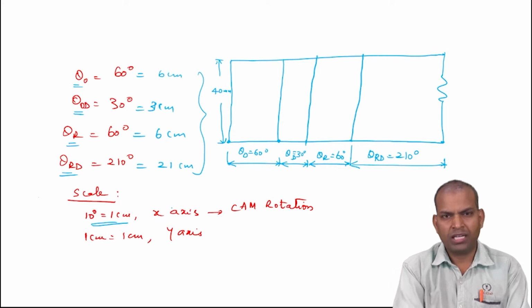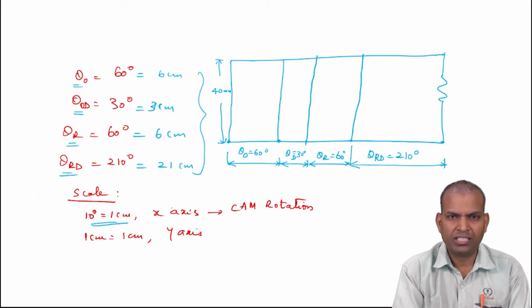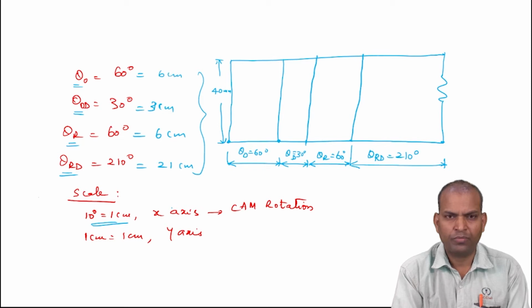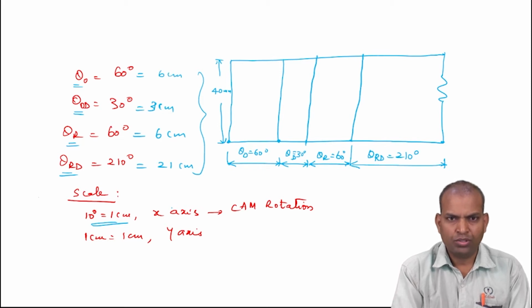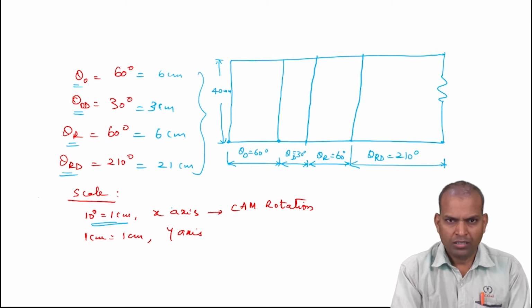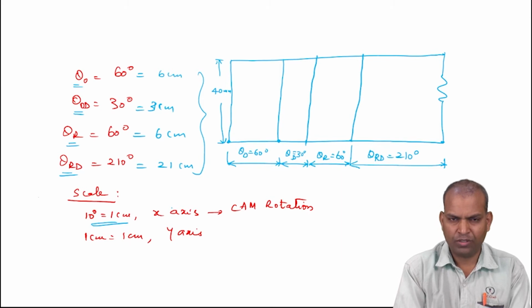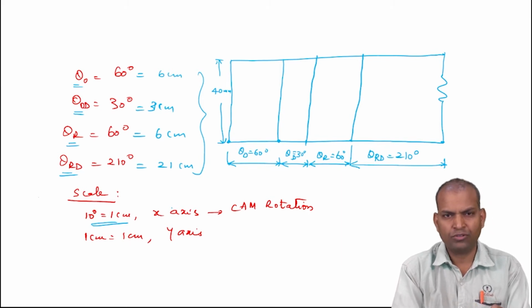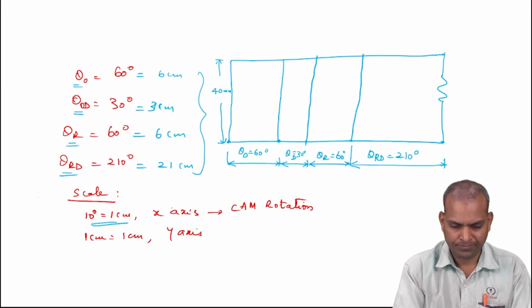And one more thing is that when accuracy improves, it also takes more time if the number of equal parts is more and more. That's why the optimum is neither 2 nor 4, similarly neither 8, but we are following only 6 equal parts. That means it takes less time and also maintains optimum accuracy.